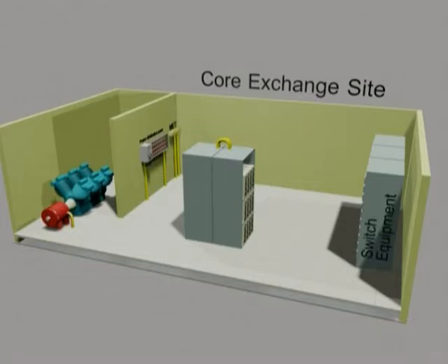One of the important components on a core site like this is the power supply equipment. You will appreciate that no operator can afford to lose a whole telephone network in the event of a power failure. The power equipment must therefore supply the switch with an uninterrupted DC power source.